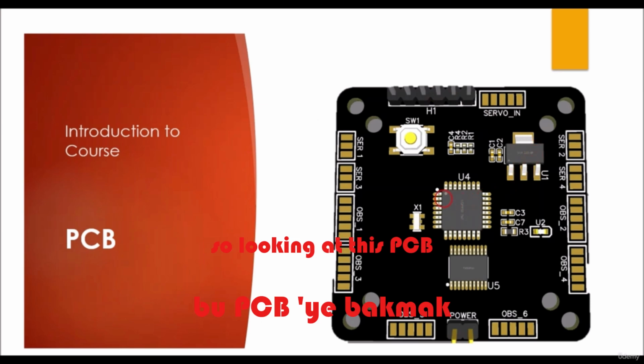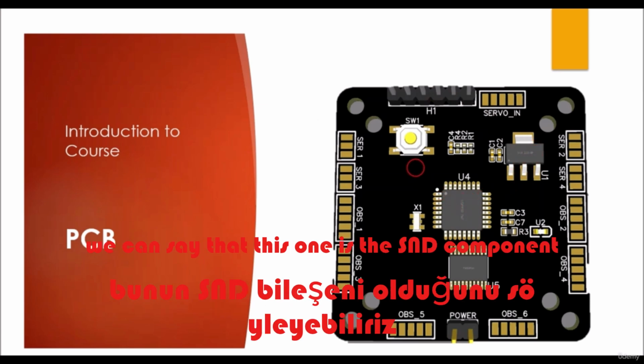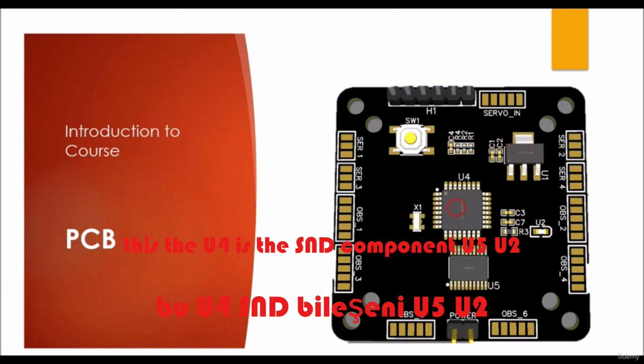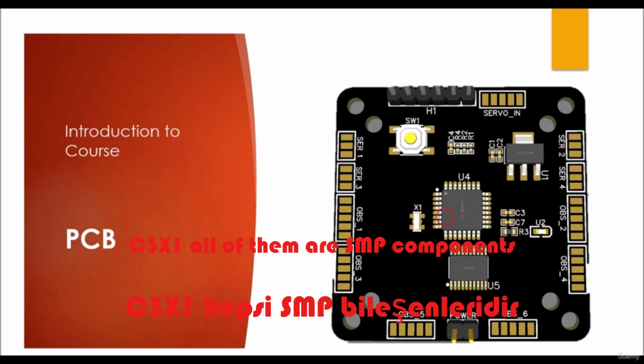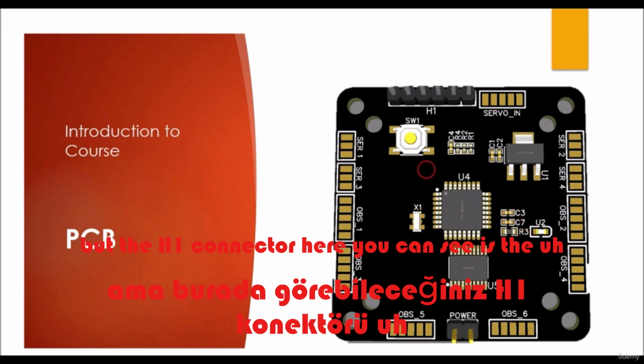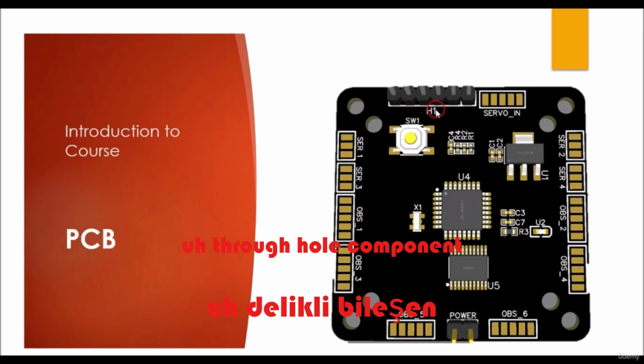So looking at this PCB, we can say that this one is an SMD component, this one is also SMD. Here U4 is an SMD component, U5, U2, R3, C7, C3, X1. All of them are SMD components, but the H1 connector here is a through-hole component.